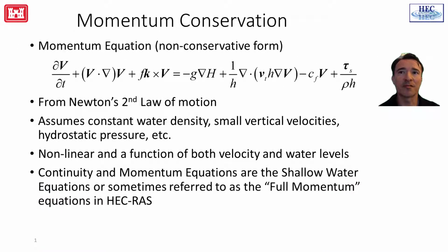This is the momentum conservation, or simply momentum, equation solved by HEC-RAS. I'll describe each term in detail in the following slides, but very quickly they are, from left to right: the temporal term, advection, Coriolis, pressure gradient, momentum diffusion, bottom friction, and wind stresses.